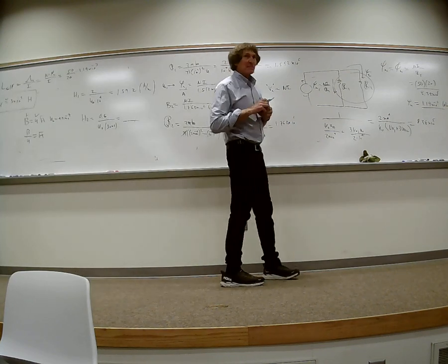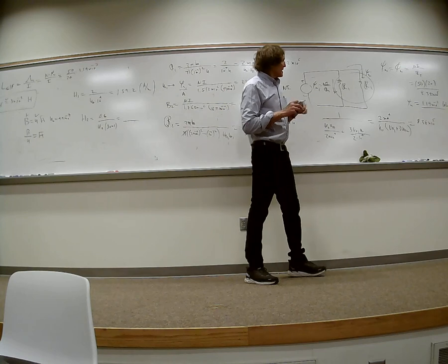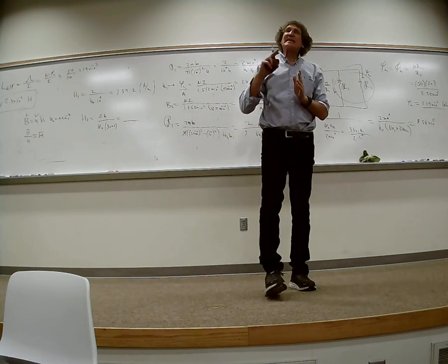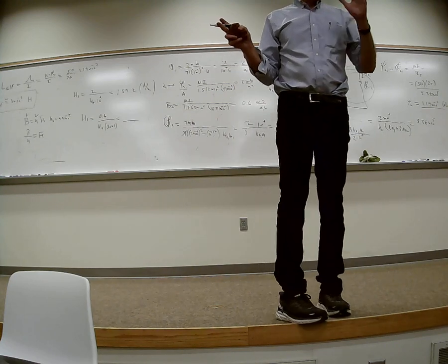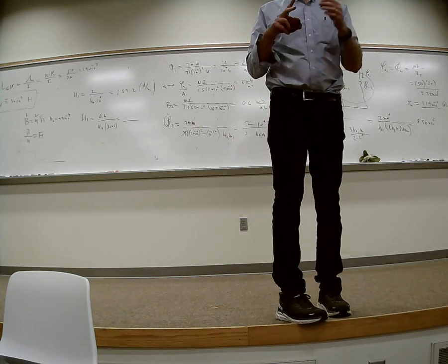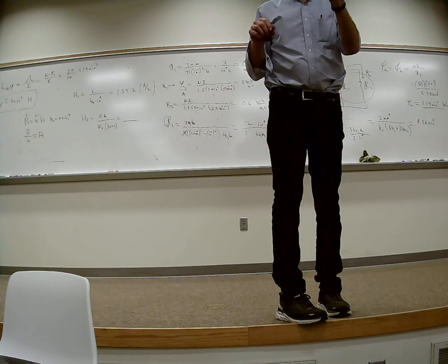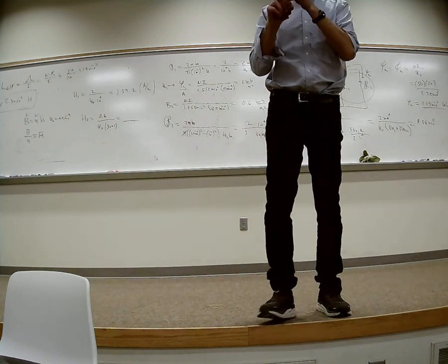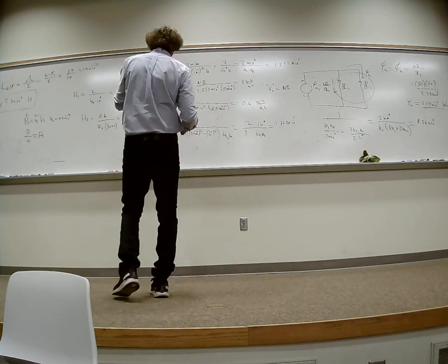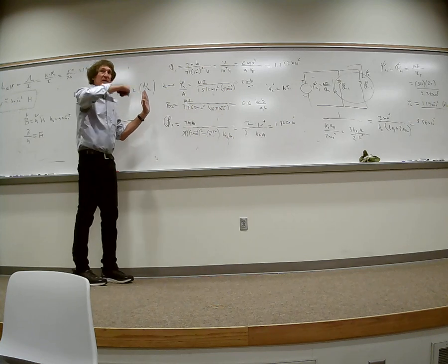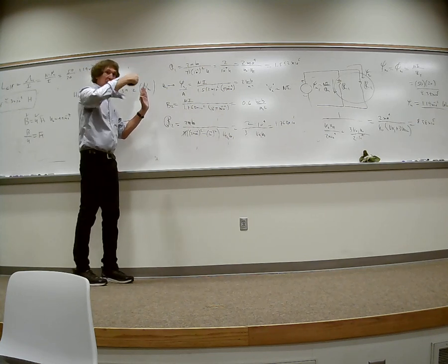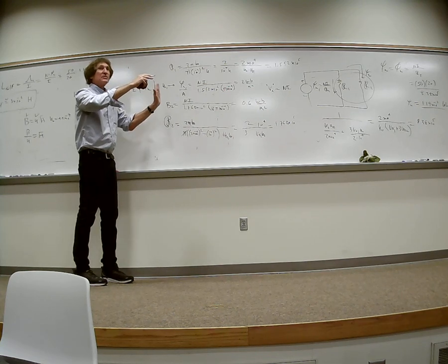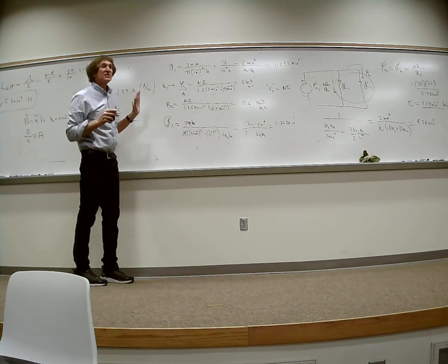All right. My point is this. Just think about it, right? Here, these are in parallel, right? Now, the H field is like the E field. Think of it that way. H parallels the E field. One thing you know about the E field is E tan 1 is E tan 2. The tangent E field is the same across a boundary. Here, I erased it, but you have a boundary where the B field is circular, and so is the H field. It's like the E field. So the H field in one region has to be the H field in the other region.